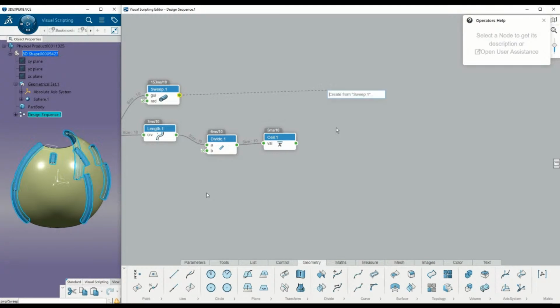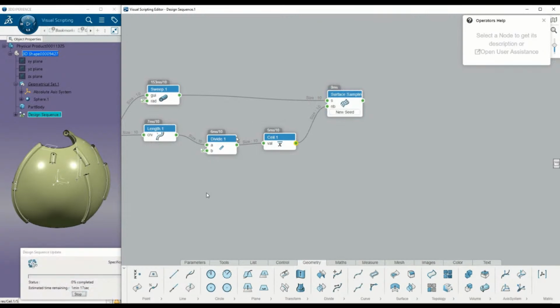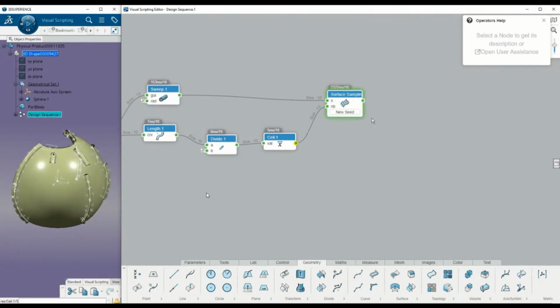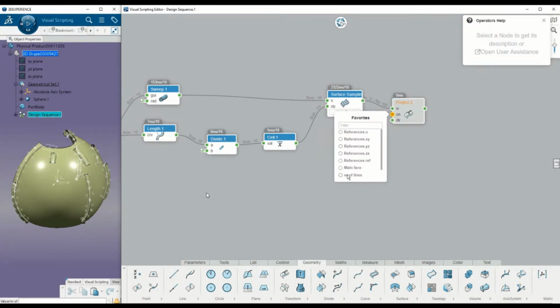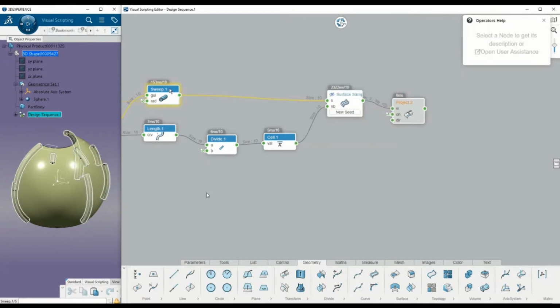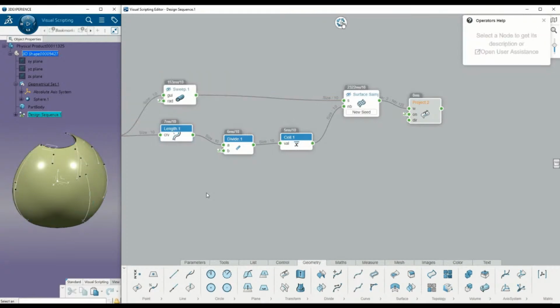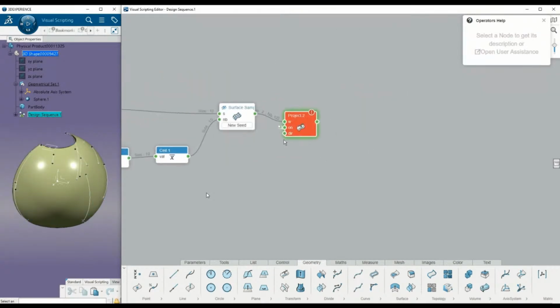So now we have the amount of elements that we want to apply here, and we will use surface sampling again on each of these elements. As you can see here, I'm not handling one element. It's not one sweep created here. It creates a list of sweeps on which we are performing specific operations. In this case, we simply created this number of elements on each of these surface samplings, and we will project it back to the surface, and you will see the result in a second.